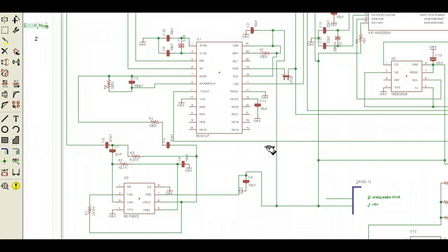In the last video we talked about, in high-level terms, how the receive portion of a TNC works. Now we're going to look at the schematic level. So the audio signal comes in right here from the receiver. And remember, there are tones in here, 1200 and 2200 Hz tones coming in. And this is just an op amp.